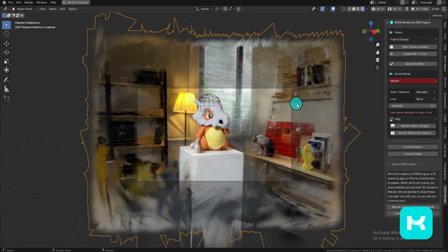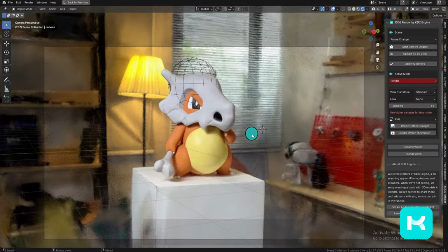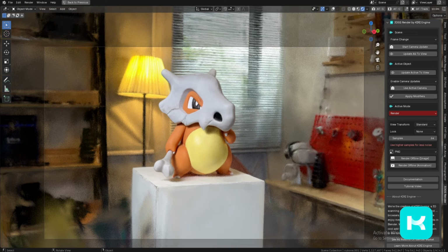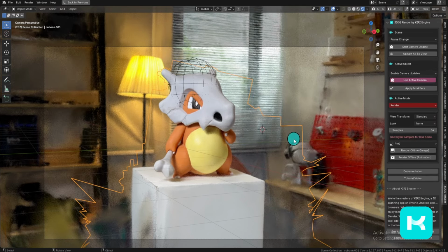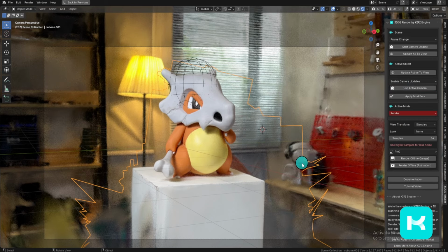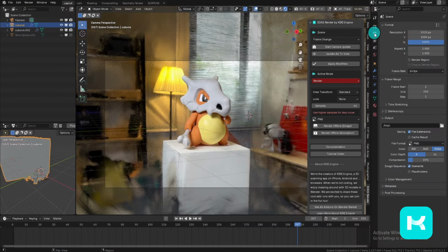Rendering 3D objects with thousands or millions of faces and many other modifiers is a very performance-hungry task. So to make rendering a little faster and more reliable, we have the render menu. Using the render settings from this menu, rather than Blender's native F12, will set all enabled 3D objects to use the active camera and will render all images offline to boost performance. The current Blender output settings will be used for all renders.